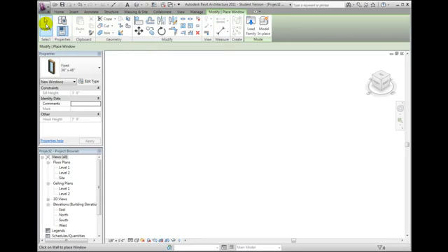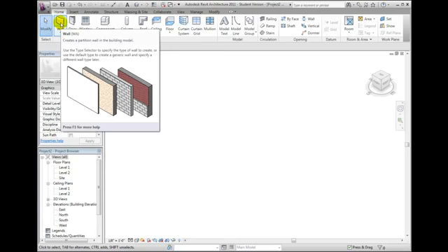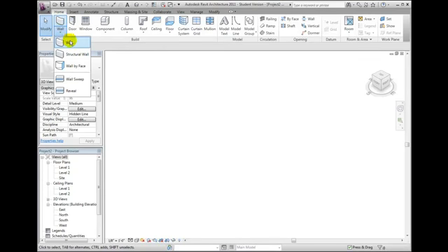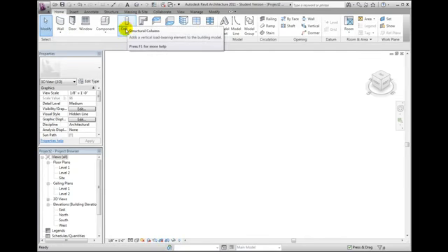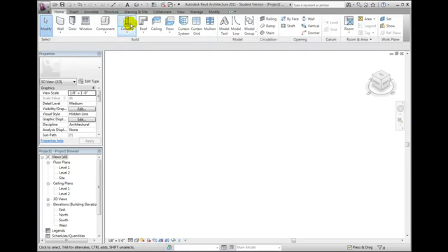A split button, like the Wall tool, has the most used tool at the top, with a drop-down button that displays additional related tools. Some split buttons, like the Column tool, will switch between the default and alternate tools. Your choice remains current after executing the tool.